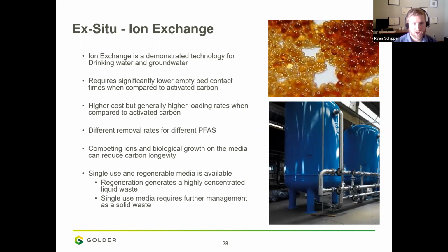There's both single-use and regenerable media available. The regeneration can create a highly concentrated liquid waste with PFAS, and the single-use media is going to require disposal or further management when it's spent.